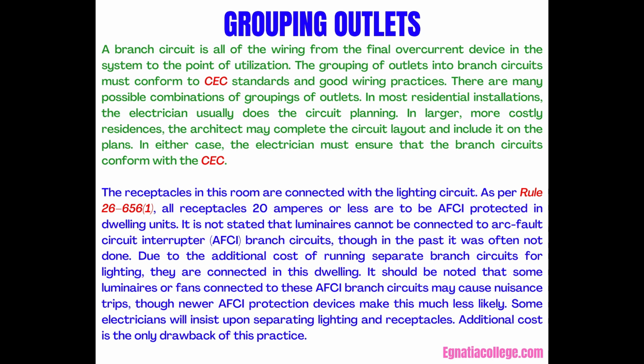It should be noted that some luminaires or fans connected to these AFCI branch circuits may cause nuisance trips, though newer AFCI protection devices make this much less likely. Some electricians will insist upon separating lighting and receptacles. Additional cost is the only drawback of this practice.